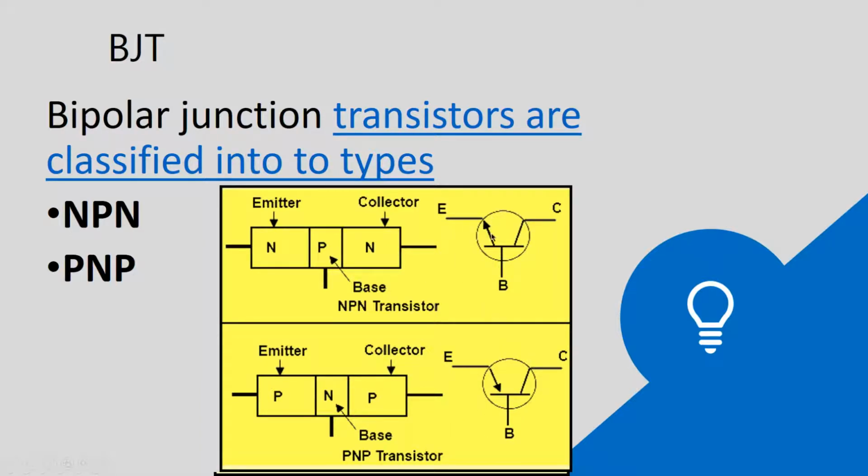So these types of switches are current controlled, unlike the other ones which we were talking about earlier. Those are mechanically controlled. So these are current controlled. You feed the current into the base of the NPN transistor, and a current is going to flow from the collector to the emitter, making the connection between the collector and the emitter. On the PNP transistor, you feed a negative current into the base of the transistor, and when you feed this negative current, it is going to flow from the emitter to the collector, and some of it is going to flow through the base to your control circuitry.